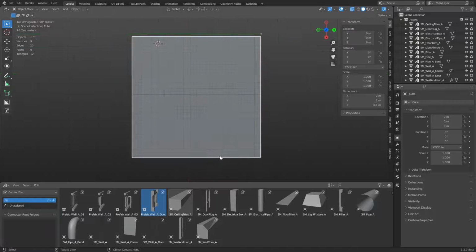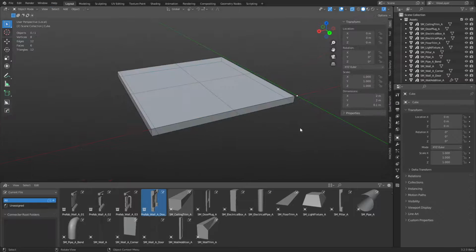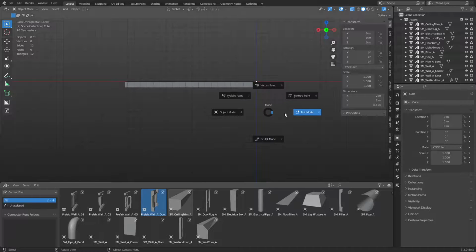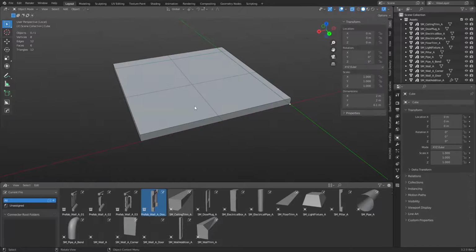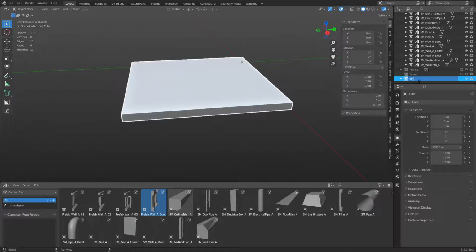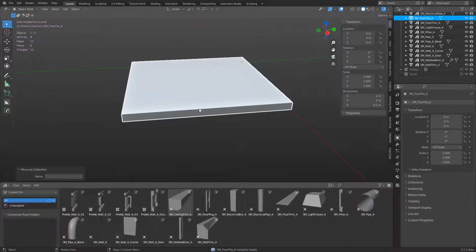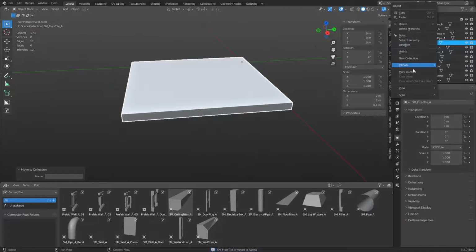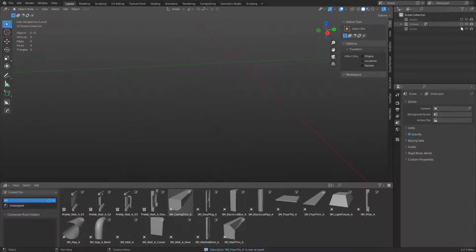Let's backspace it real quick, slash isolate it. It's definitely not lined up right. Okay. Still not lined up right, because apparently I didn't do that correctly. And it needs to go up 10 centimeters. There we go. And so we got the floor unit. Let's go ahead and tag this as static mesh floor file A. We'll go ahead and move this to assets. It goes up to assets here. We can right click, mark as asset. Done. All right. Good idea to save your scene, by the way.